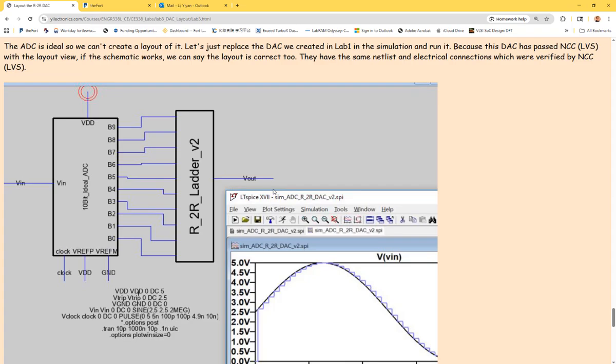And then we wrap these up in another box, okay? So we know this passes DRC, passes the LVS, is clean, it's all aligned with each other. So we put this one as one box, we call it DAC. In a future chip design, we need 100 DACs. So we just directly use 100 of these boxes instead of drawing every single resistor by ourselves, manually for each one.